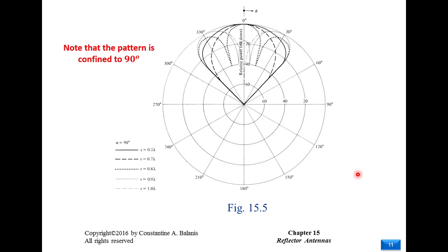And one thing regarding the radiation patterns that I saw in the homeworks, that for example, if we are scanning for theta, you must pay attention that theta changes from 0 to 180. There is no reason to go from 0 to 360. And also, the radiation pattern is a single value. You can't see a loop inside a loop, because, for example, let me draw this. So for example, we can't draw a radiation pattern like this.